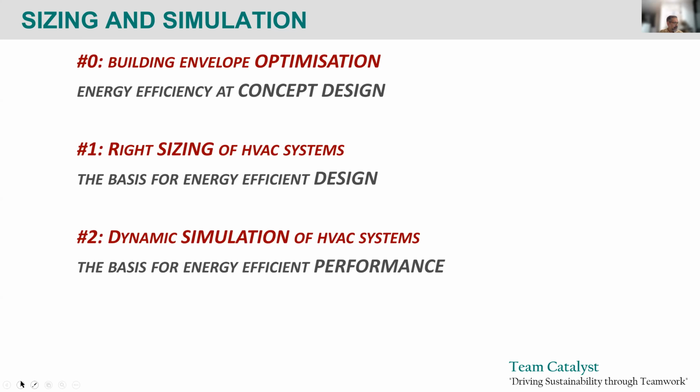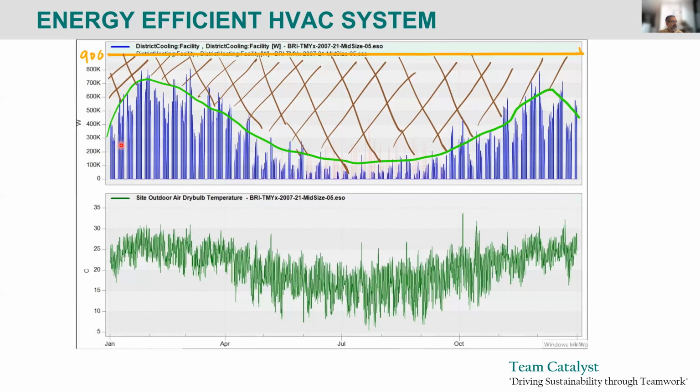Anyway, when you run a simulation, you can pull out hourly thermal loads for the building, and these blue lines are that, right? This is for cooling. And if you look carefully, you can see some shaded red spikes, and that's the heating. Now, Wollongong is a very coastal town. It's quite a moderate town, so there's hardly much heating. Most of it is in the cooling part.